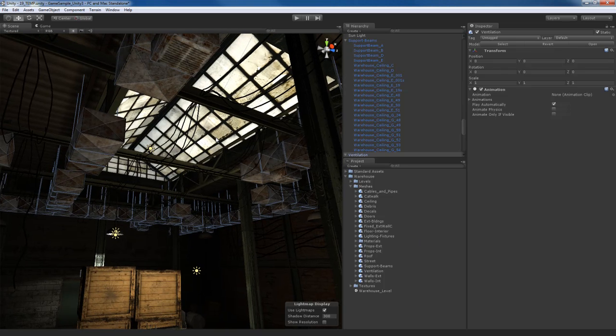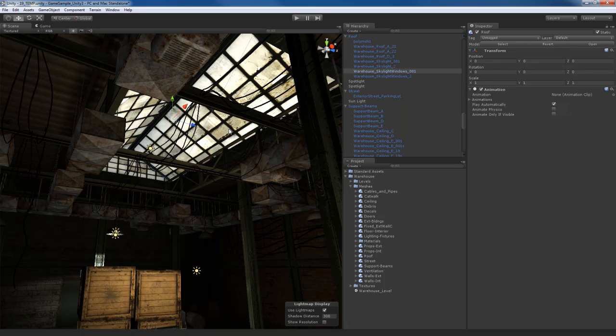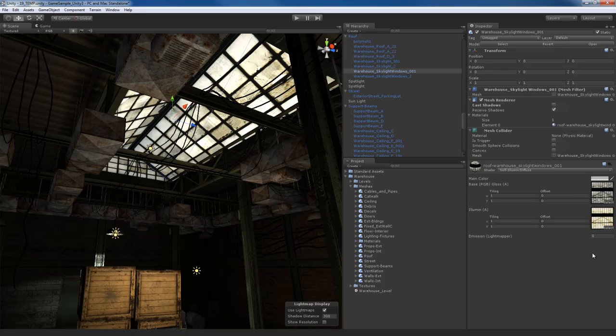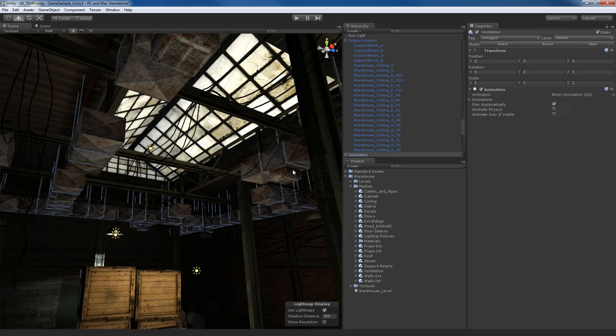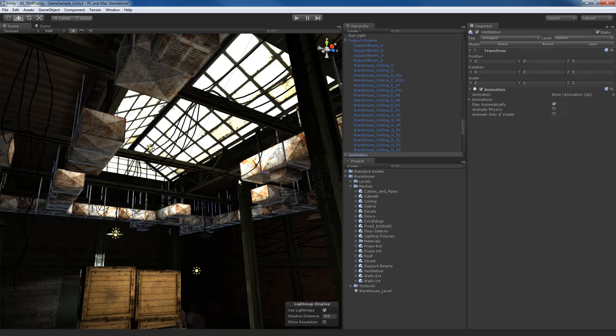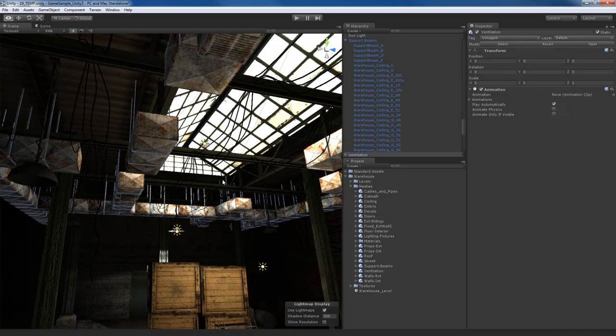All right, what I'm going to do is take that material. So I'm going to select the window pane here, and I'm going to take that emission parameter and crank that up to something pretty high, something like 50. And I'm going to take those same objects, the window panels and the air ducts over here, just so you can see how this works. I'm going to hit bake selected. So it finished. Now you can clearly see there's a huge difference.